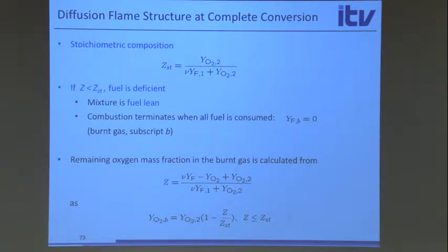So very small, because the mixture fraction gives you a mass ratio. And we said earlier, you always need a lot of oxygen, a lot of air, for a certain mass of fuel, which is why the mass fraction of fuel is very small for stoichiometric conditions. For hydrogen, it's even much smaller.